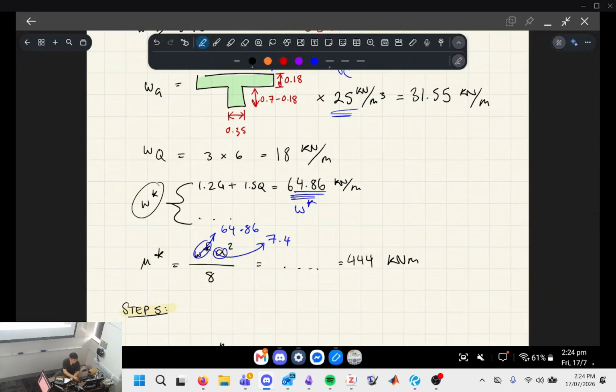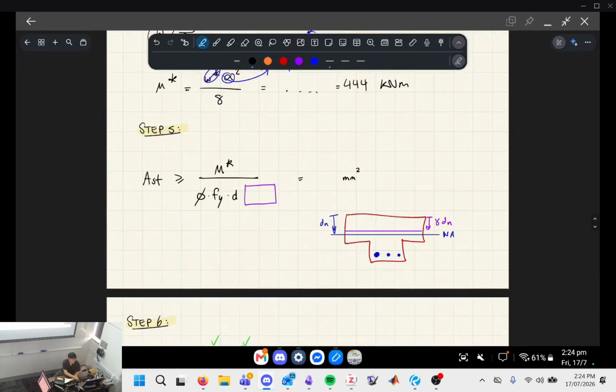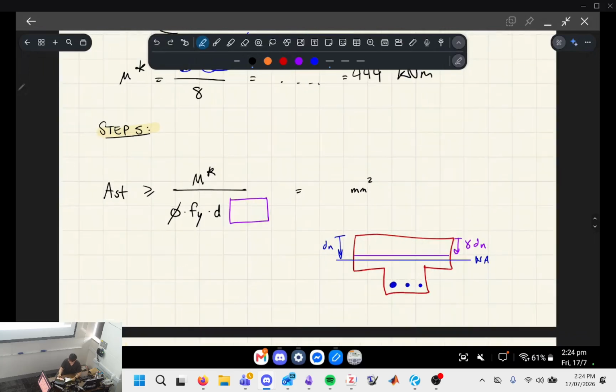Now our next step in our cookbook is the initial steel sizing. All we've done so far is the concrete; we've just chosen the concrete's dimensions. We still have to do the steel. Here's the formula for sizing the steel. This is the initial sizing formula for the steel. We actually know the bending moment for sure now, so we can plug that in.